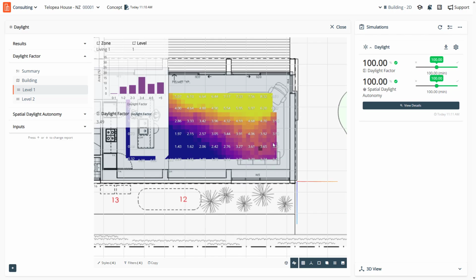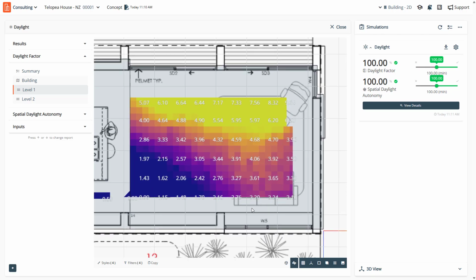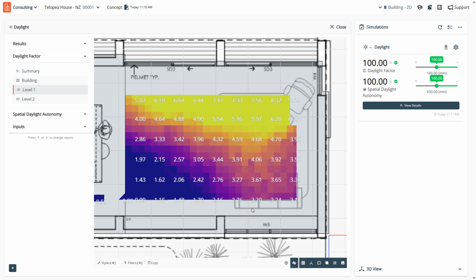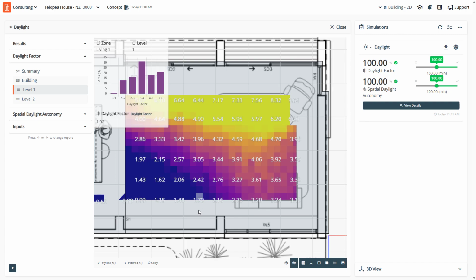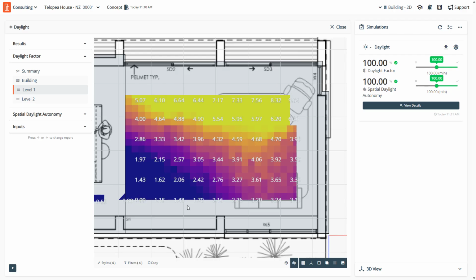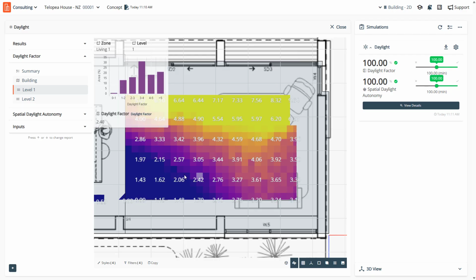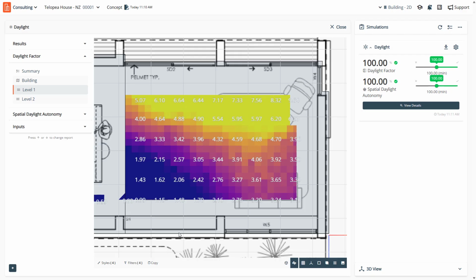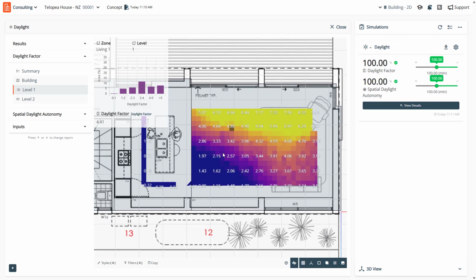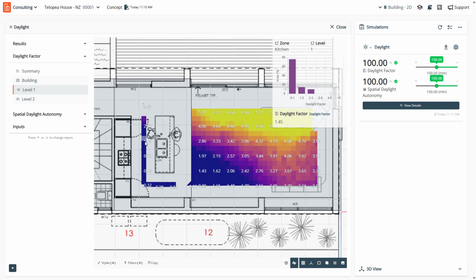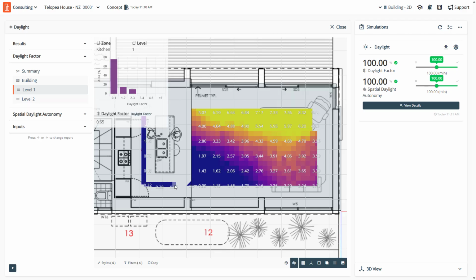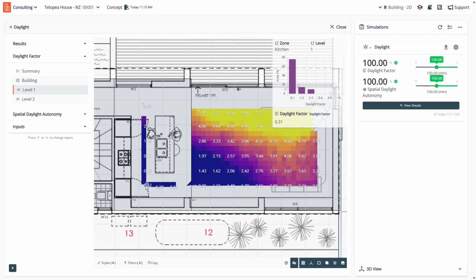Once set up correctly, you'll be able to see the daylight distribution across the grid plane with the numerical values representing each daylight grid point. In the case of the automatic grid here, and this is the grid that was created manually and brought in as a custom grid, this is the reason why we brought it in here, because we need to see the data points all the way down through here to see what the minimum daylight factor is in these spaces here.